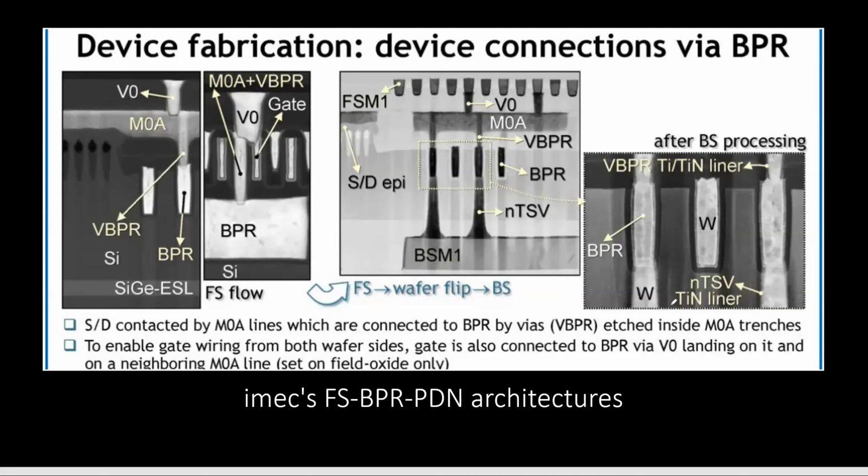But this paper is only to demonstrate. You don't have the key process technology to do everything POR in a foundry. There's no way you can do that. Right? They are not into the yield business. They're here to demonstrate. Okay. And then the one interesting thing is the silicon germanium etch stop layer, which I will explain later. They use that to stop the etching.